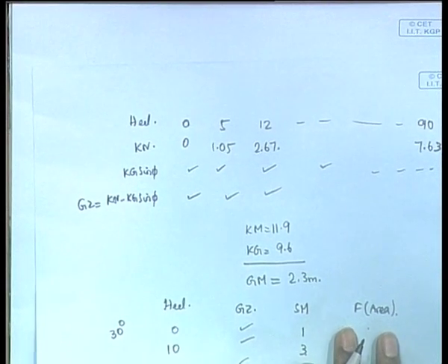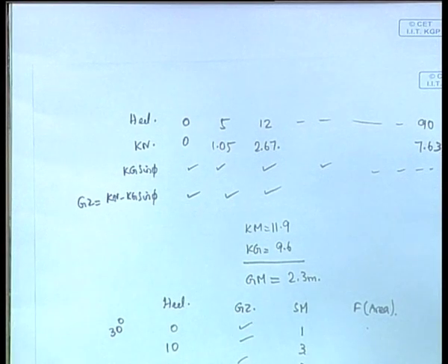Oh, okay. The only way when you are given a problem like this is you have to draw the GZ curve. So, you have to do some kind of approximation. What they have done here is you take up to 30, that is no problem here. From 30 to 40 you have to make some kind of rectangle, okay, and make an assumption like that. They have made a rectangle and roughly said this must be the area and subtracted that from 45. That is all right. At any rate you have to be ready to draw the GZ curve.